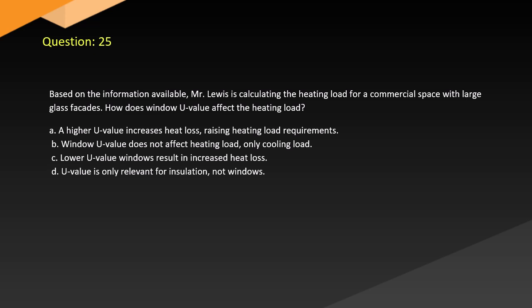Question 25. Based on the information available, Mr. Lewis is calculating the heating load for a commercial space with large glass facades. How does window U-value affect the heating load? A. A high U-value increases heat loss, raising heating load requirements.